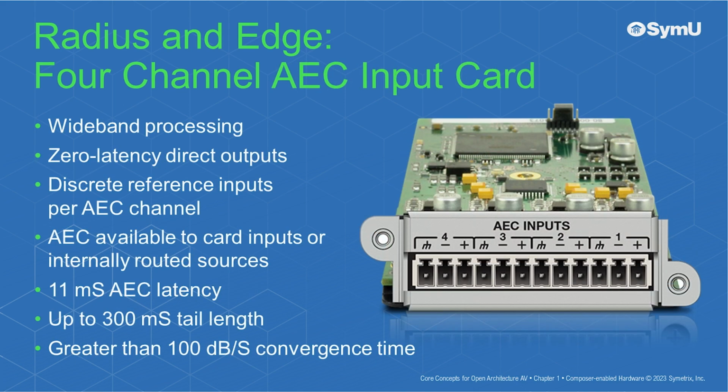The 4-channel AEC input card offers wideband processing, zero latency direct outputs, and discrete reference inputs per AEC channel. AEC processing is available to the card's direct inputs or internally routed sources. 11 milliseconds AEC latency, up to 300 millisecond tail length, and greater than 100 dB per second convergence time.